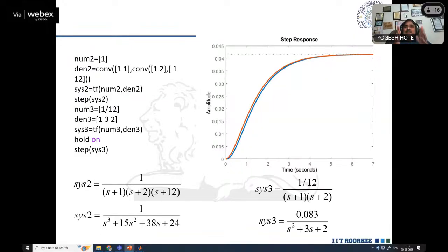So this is, we can say, a state space model from the given transfer function. So what is the transfer function and what is the state space? Those are learning for the first time. Transfer function means we have input and output. We don't know what's going on internally. State space means what is going on internally. That is called a state space model. We know all internal things. So the transfer function is comparatively simpler because we have to think about input and output only. State space means along with input and output, whatever the internal things, we have to take care of.